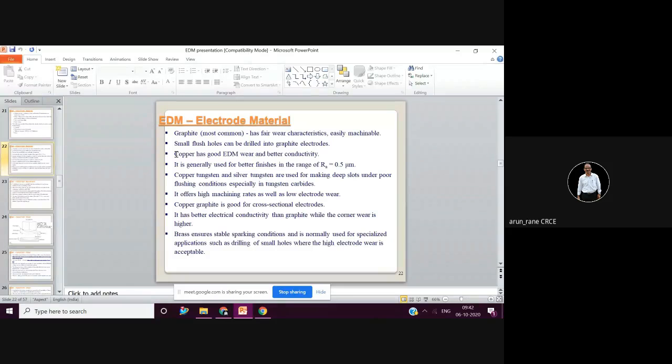Of course, you have to take care of safety issues because we are talking about 10,000 degrees Celsius temperature, and fire should not take place. So you should have sensors to detect fire and smoke, to enable fire extinguishers, and to pause the machining and again resume the machining. All these adaptive controls, or smart machining, should be there if you want to leave the machine unmanned.